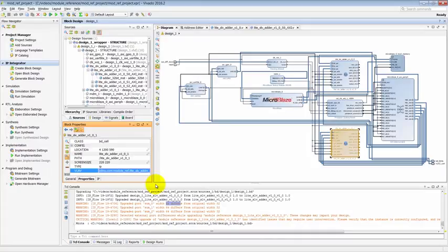The only supported languages are VHDL and Verilog. SystemVerilog and VHDL 2008 are not supported at the top level of the RTL module, although SystemVerilog support will be provided in future releases. The Vivado IP Integrator does not let you associate an XDC file with a module reference as it does with an IP. You can synthesize the module as an OOC module, however, you cannot associate XDC files with the module. XDC files must be added to the Vivado project separately.